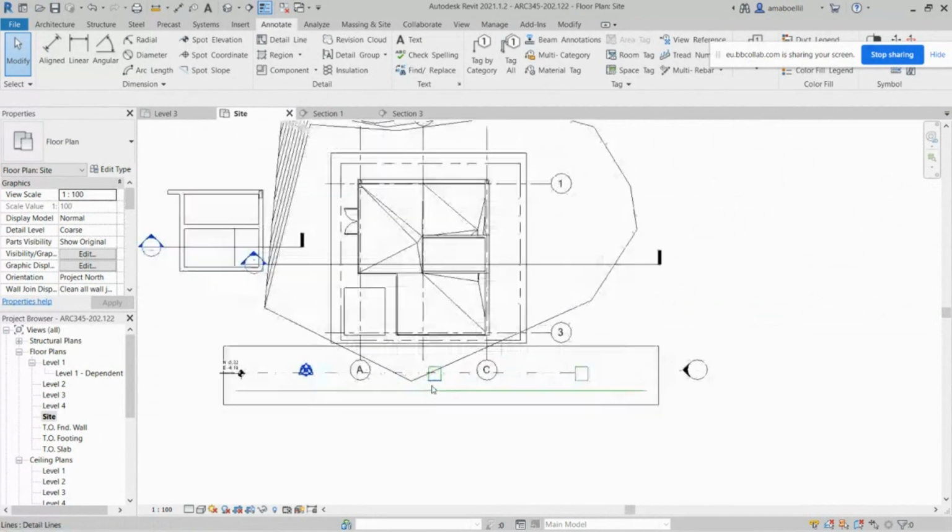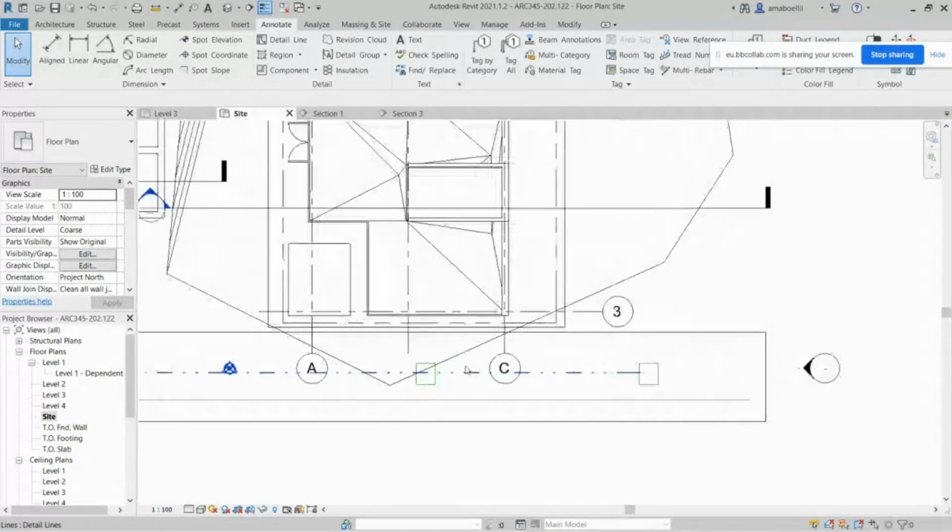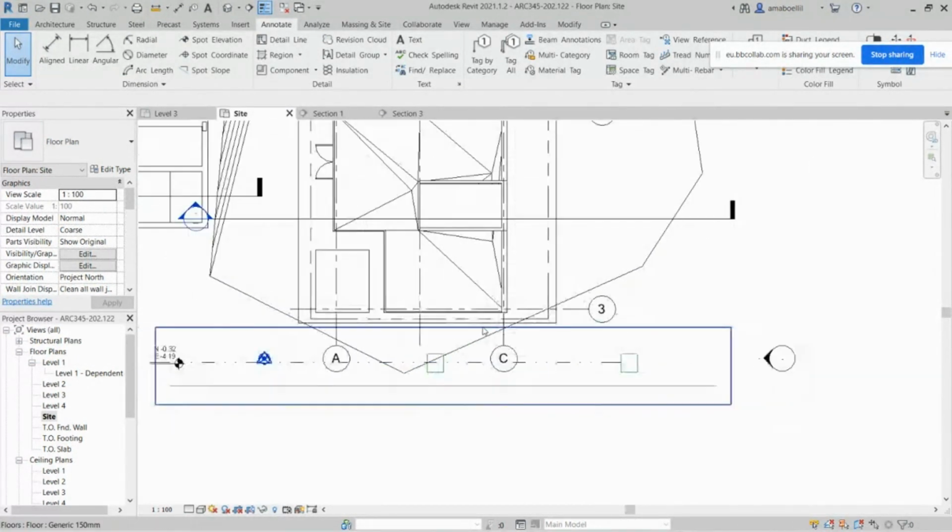You're not asked to do something like this, but at least you show the lines with the manholes and then the feeder to the building, so that you have the line passing like this. Where is the connection to the building? You have to run another line that connects to the building here to express the feeder of water, light current and electricity, and then taking away the sewer system.